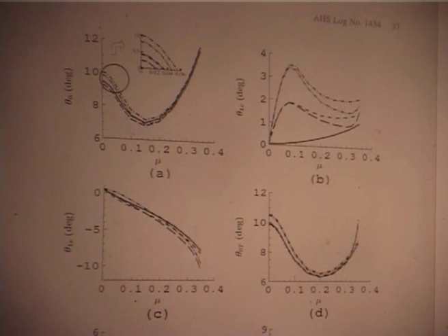Now, why does this curve shoot up like this? That is because of the fuselage drag. If you reduce the drag of the fuselage, but how do you reduce it? That is the problem. That is why that F which I showed you, the equivalent flat plate area for the helicopter, has to be brought down somehow, then the curve may tilt and you can go further. If it is there, you just cannot trim, the drag will shoot very high. That is one of the key things.